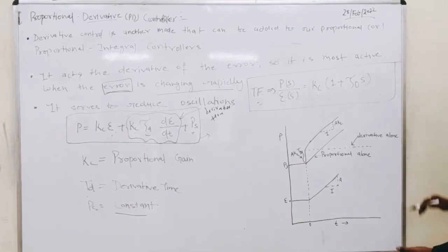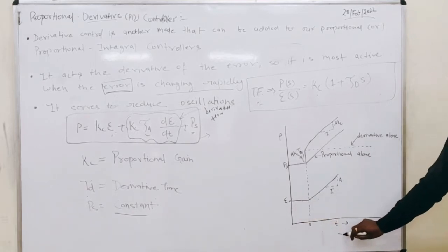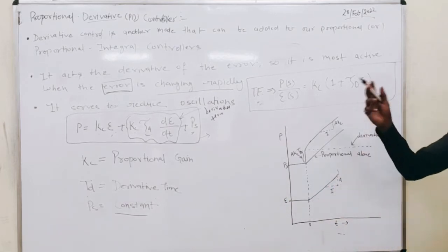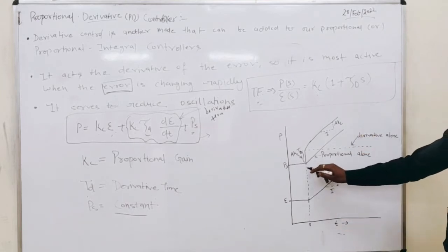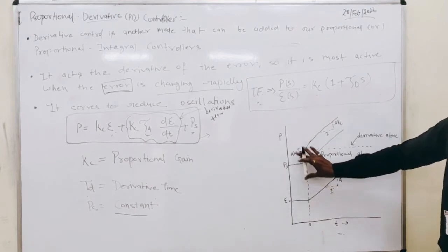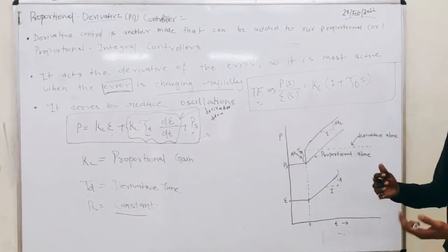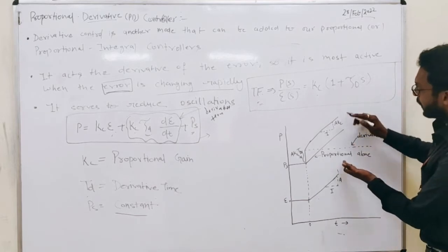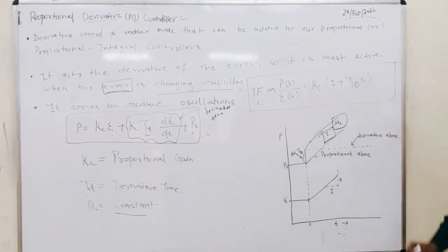And if you see the action of the proportional derivative controller, the graph looks like this. Here, already we have the error value, we are drawing a graph between t and the error value, and already we are getting an error value that we have seen in the proportional controller. To that we are adding the derivative controller, which finds the rapid change or the oscillation in the output, whatever error is produced, that will be found by the derivative controller.